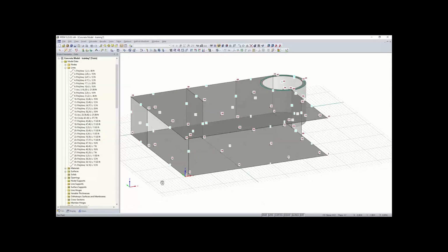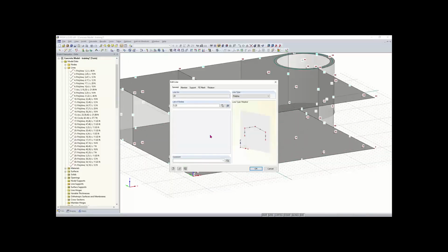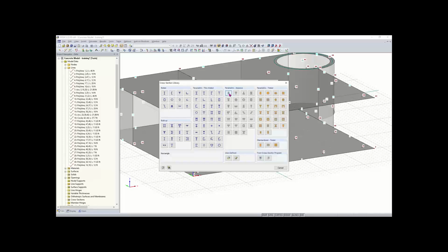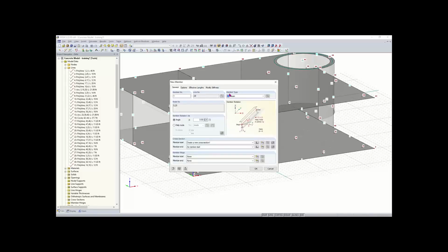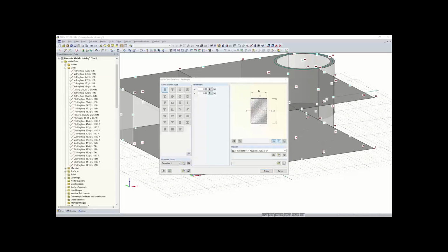And then what you can do is you can turn lines into members basically by double clicking on them, and then going to member. There's some tabs up here. If you go to the member tab and then available, once you hit available, it's going to ask you, okay, what cross section do you want this to be defined as? We'll go to import cross section library, and this is going to be a rectangular parametric concrete massive section. And the dimensions of this are going to be 14 inches by 14 inches.